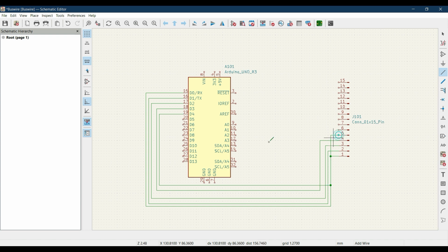and 5, and if I keep on adding, you are seeing that we have encountered a problem that there are a number of wires going from this side towards this side, and you can also see over here that accidentally we have connected pin number 1 and pin number 5. Now an alternative way is to use bus wires that will help us to organize this schematic.